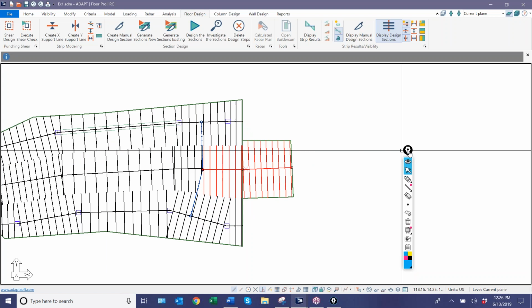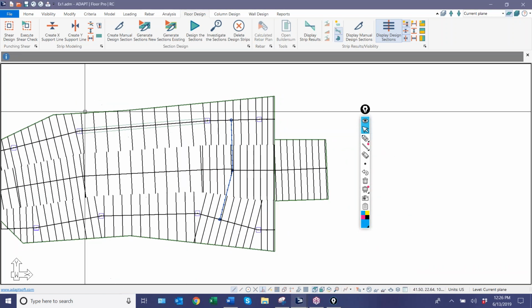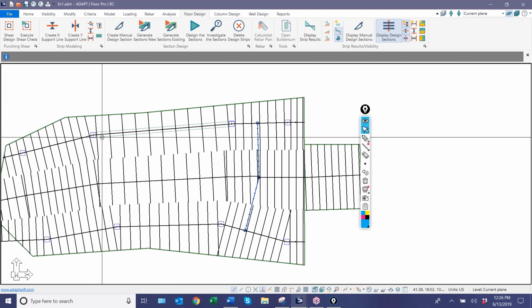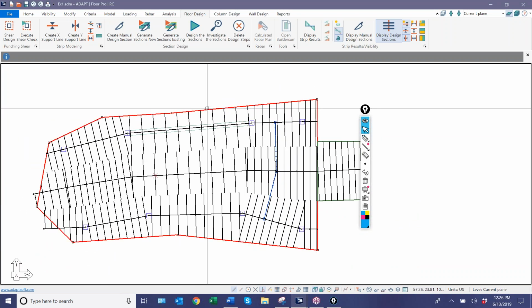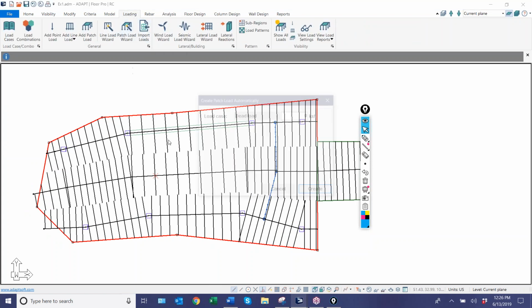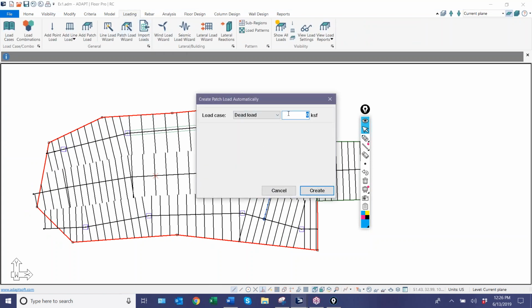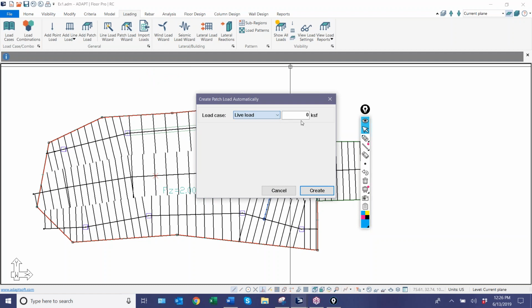The next thing we'll discuss is this beam. I've been talking about it, but I haven't really talked about it, so we'll look at this beam. Now, right now, if I design, let me just add a little bit of load to this slab so we'll get some reinforcement demand. Let me add 20 PSF dead, and I'll add a 100 PSF live.